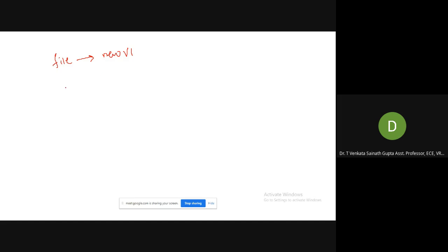After this, you will get two windows. So to align these two windows, you need to press Control plus T. So whenever you press these two buttons, the windows will be aligned side by side. So the two windows that you will get are front panel and block diagram.